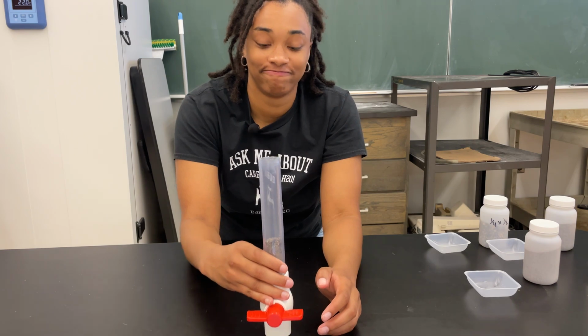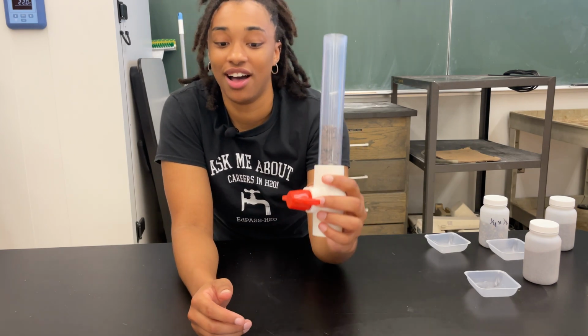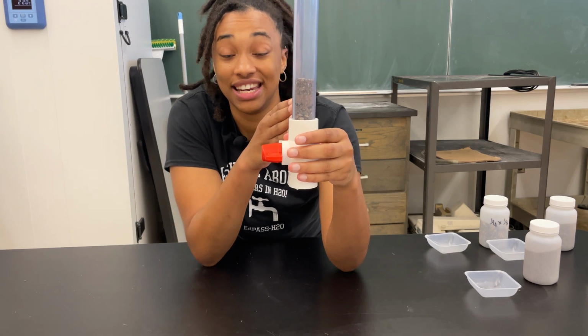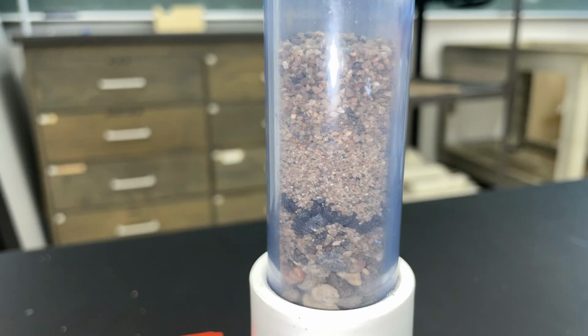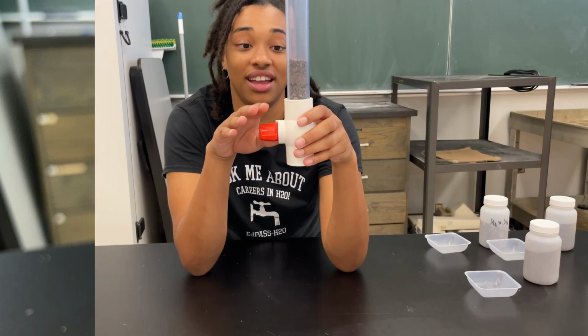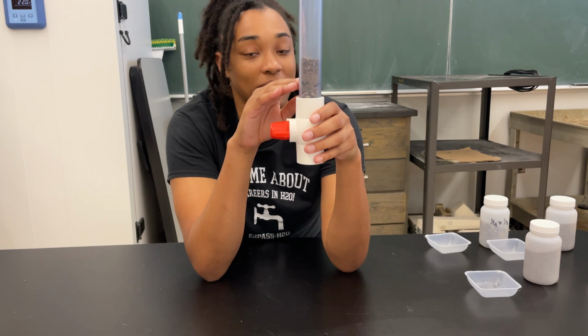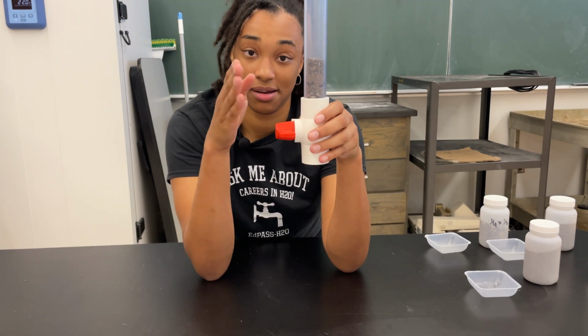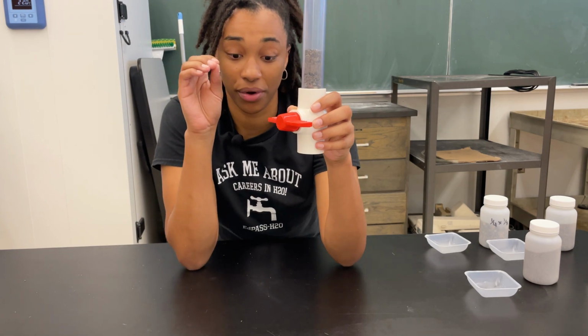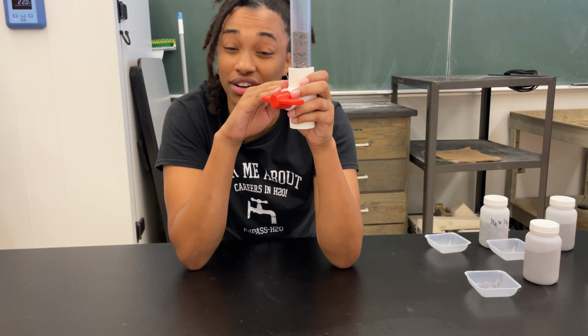Let's take a look at an example of one. You don't have to go anywhere, I already have one built here. But I want you all to notice the variety of medias used in this filter and the amount. Initially we have our support layer with our large and medium-sized rock, followed by our granulated activated charcoal, which is used for taste and odor control. Yes, I know you guys got that right. Followed by sand, the 40 by 50 media on top, and possibly 60 by 80 or 80 by 120 on top of the sand. The most important thing to note here is the order of the media.